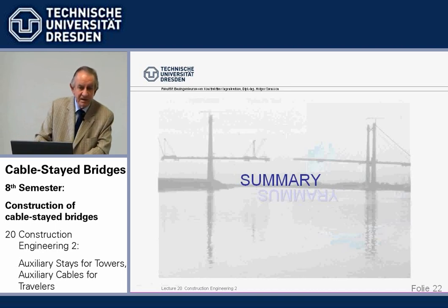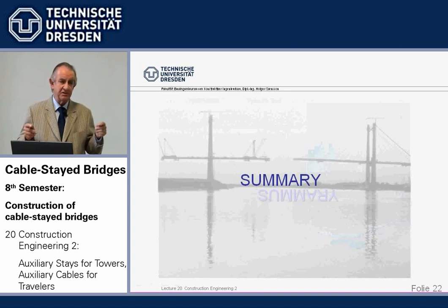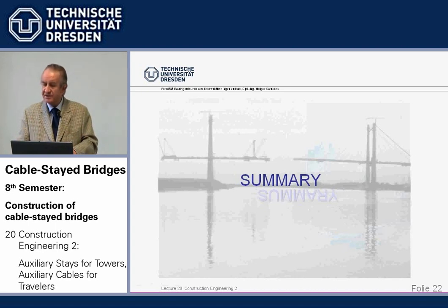And today I tried to familiarize you with how to check stresses during construction for a chosen construction method, and how to tell the site what to check in order to be sure to arrive where we want to. At the final stage, after shrinkage and creep, we cannot do these calculations by hand because here it has to be precise and we have a highly statically indeterminate system.